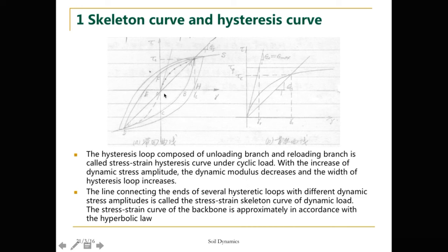And we know as the strain develops, we can find the inclination rate of this line will decrease, and this line describes the average dynamic modulus. Then the dynamic modulus decreases and decreases with the stress increase.